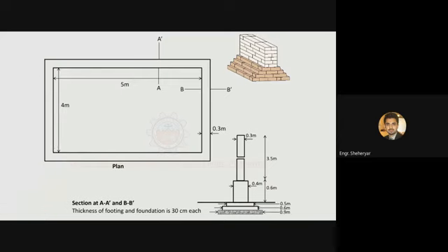When you are taking the length of this wall as long wall, measuring it from this exterior edge to the other exterior edge, and this wall from inner edge to inner edge, and then this wall, because it is a long wall, from exterior edge to exterior edge, you can see that the areas do not overlap and there will be no repetition of quantities in this method.